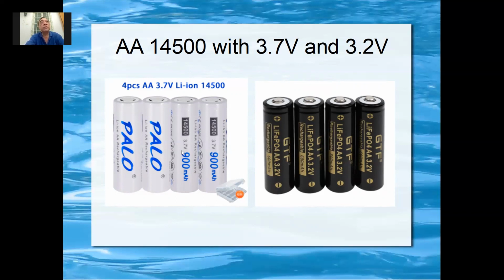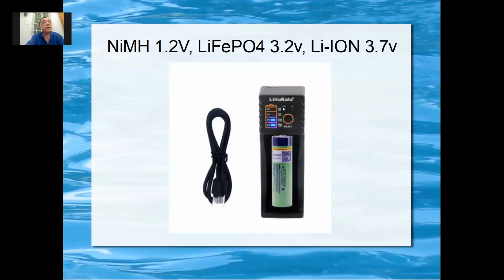But once you have all this battery, 3.7, 3.2, you must have a charger. Okay, I use this charger, little color. I just plug it in and it charges by itself. It auto detects, it will charge. If it fails to auto detect, because sometimes your battery voltage is too low, very long didn't use for many months, and the voltage discharges until too low, then it cannot recognize. Then you press this button to select which type of battery it is, and then you'll charge to that battery.